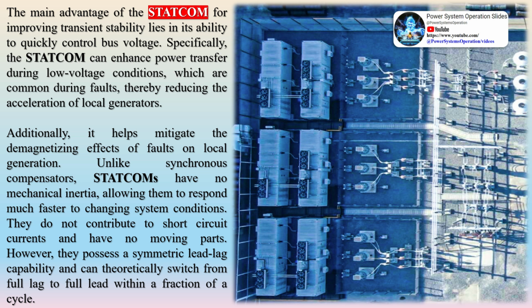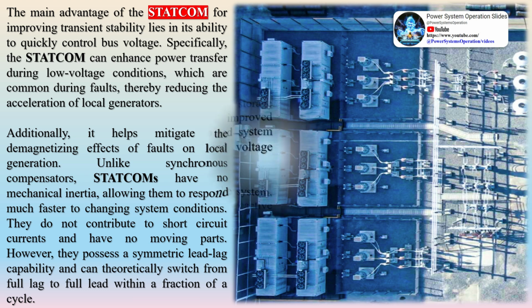On the other hand, mechanically switched reactors and capacitors can be added to optimize slow response performance and provide additional steady-state capacity as required by, e.g., typical intraday load flow changes.